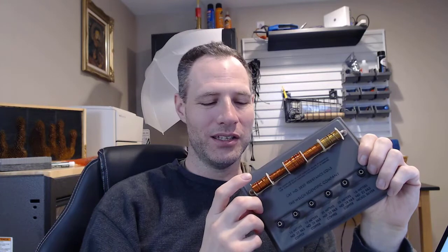Okay, so the first step is to set these coils up in a circuit with a power supply to supply voltage, and two digital multimeters, one set up as an ammeter to measure the current that flows through the coil, and the other set up as a voltmeter to measure the voltage drop across the coil. Then we'll have voltage and current, and we'll do linear regression to figure out resistance. And once we have resistance, you'll be able to calculate resistivity. All right, so let's do this.